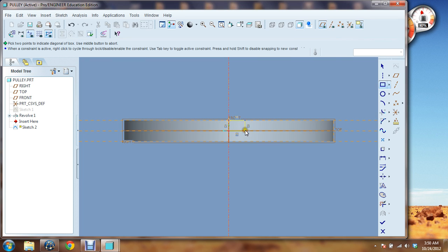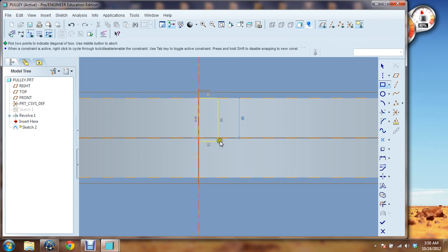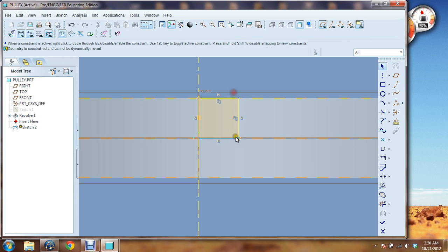And I'm going to bring this down here, and you notice we can lock to all the stuff we've noticed we can lock to, these lines, but now what it's trying to do is make these equal length. That's what those L's mean. We can do that, or we can come out here. We're going to go ahead and let it lock to be equal length. So I'm going to click that and middle mouse. And if you don't want that, remember, you can just come to these constraints, click them and then hit delete on your keyboard, and it will get rid of that constraint, because now I can't actually do anything with this. So remember, you can just click that and then hit delete, and it will go away if that's not what you want.